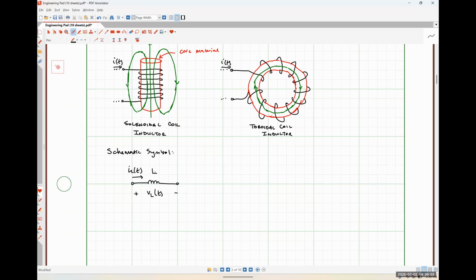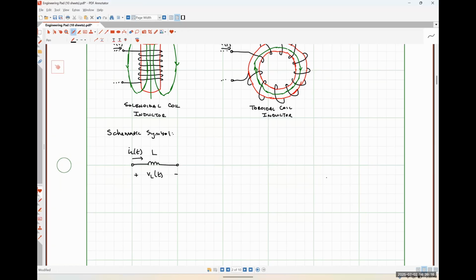And again, this has some background electromagnetic field theory that you guys aren't going to be super aware of, so I'm just going to gloss over a lot of it. But essentially, what we have is a circuit element whose operation is defined by Faraday's law of induction. Okay. So Faraday's law of induction says that an electromotive force, that's script E, is going to be equal to the change in magnetic flux with respect to time.